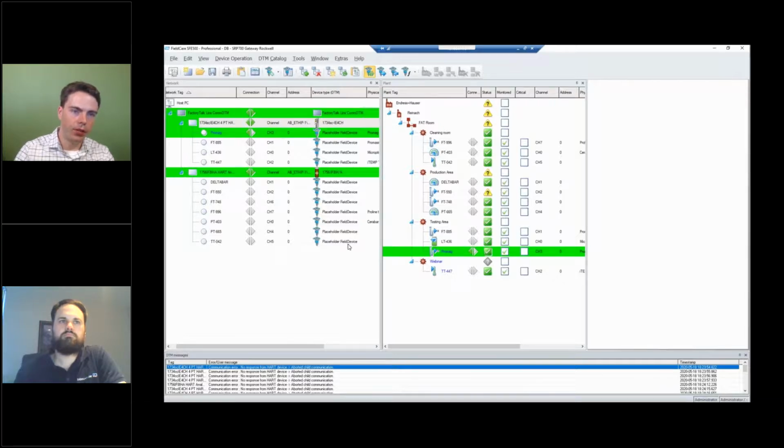With this solution, we have the monitoring of the diagnostic statuses, and the navigation is not done here in FieldCare. So you have that web page that everyone who has access to that page can open. You can also restrict it if you like, but it's very easy to access. So SRP 700 is a client-server version of FieldCare, if you want to say so, with a centralized server that collects all the data and stores it in a centralized database, and clients that can access it. That's the difference between FieldCare as a product and the SRP 700.